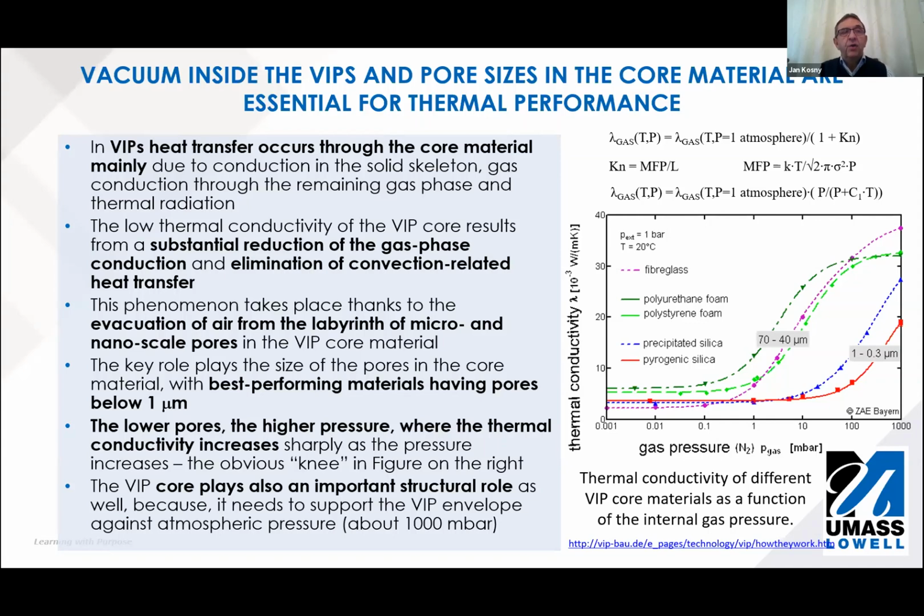And it is showing that relation for several types of materials, coming from very low size pore materials, like for example, aerogels, going back left side into the materials of much higher size of pores in the range well over 100 micrometers. The major message from that chart is that materials with very low size of the pores, well below 1 micron, need much less vacuum to perform very well, to reach very low level of thermal conductivity.